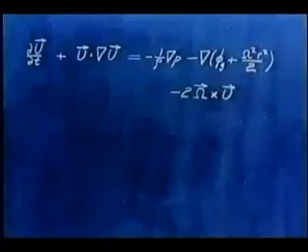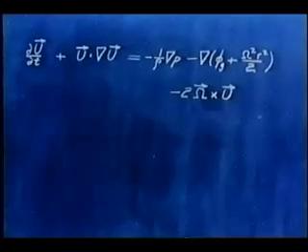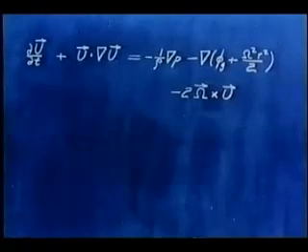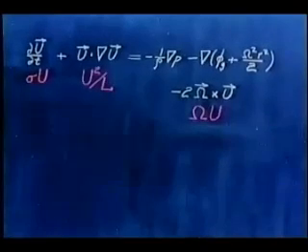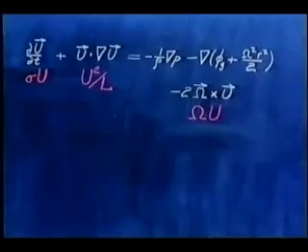Two dimensionless parameters characterize the relative importance of fluid accelerations as against Coriolis forces. They are the Rossby number and the frequency ratio. These parameters arise naturally when one estimates orders of magnitude of the terms in the equation of relative motion. The required terms are of these orders. Sigma is a characteristic frequency, U is a characteristic fluid velocity, and L is a characteristic length.